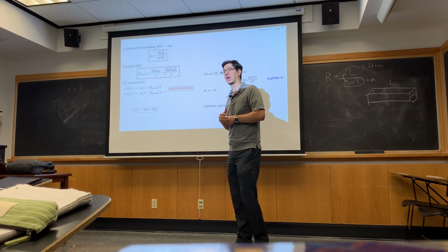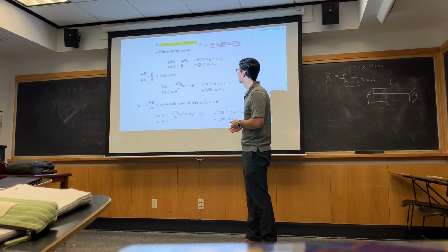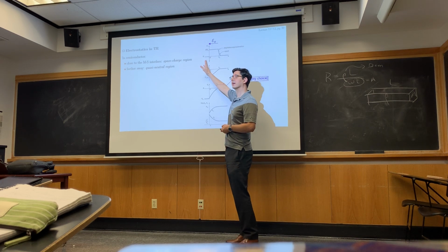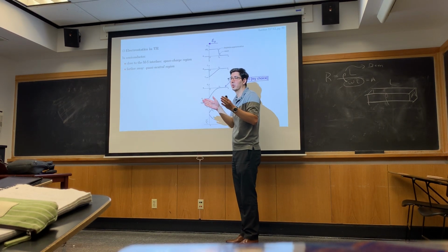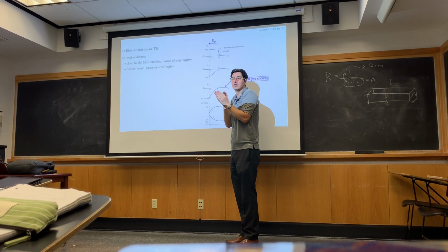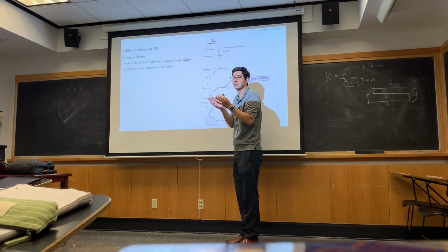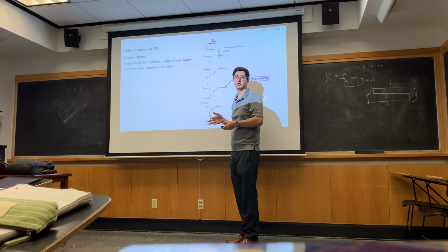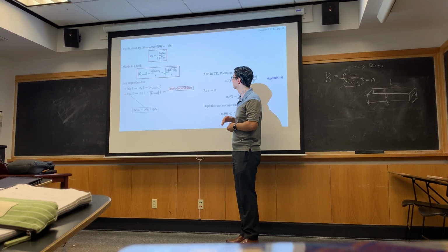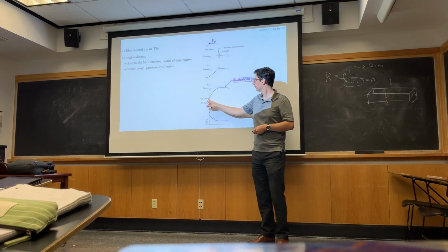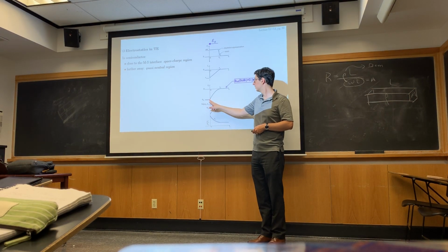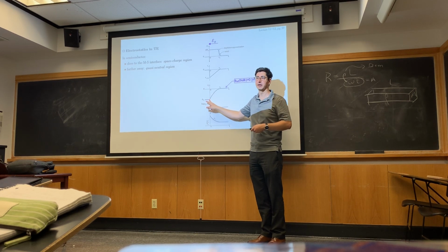You can convince yourself of that, right? If you draw this spike and give it equal and opposite charge, you'll see that you could give that spike some width, but as you take that spike's width down to 0, but keep the area the same, there's no potential drop on that side. Okay, so we know what the potential is right at 0, it's negative phi bi here.